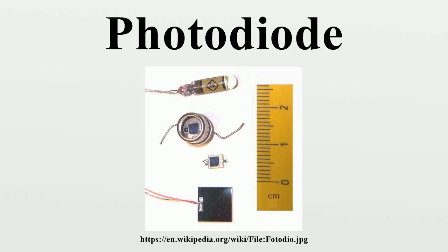Unwanted photodiode effects. Any p-n junction, if illuminated, is potentially a photodiode. Semiconductor devices such as transistors and ICs contain p-n junctions, and will not function correctly if they are illuminated by unwanted electromagnetic radiation of wavelength suitable to produce a photocurrent. This is avoided by encapsulating devices in opaque housings. If these housings are not completely opaque to high-energy radiation, transistors and ICs can malfunction due to induced photocurrents. Background radiation from the packaging is also significant. Radiation hardening mitigates these effects.